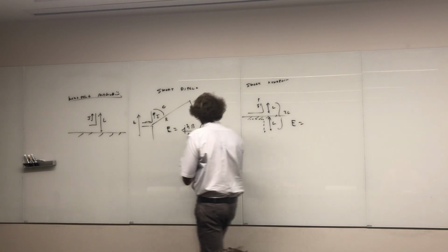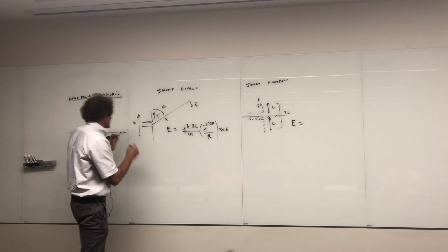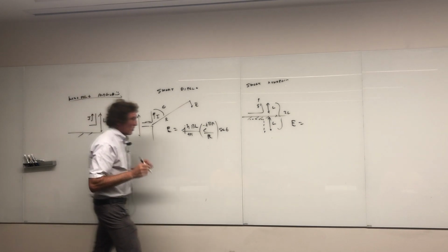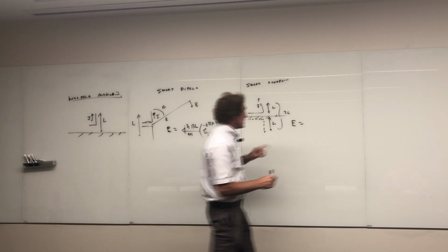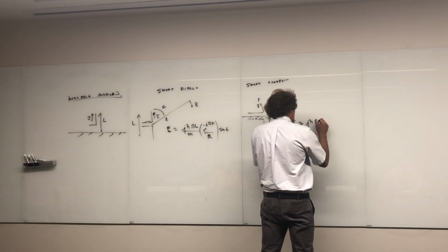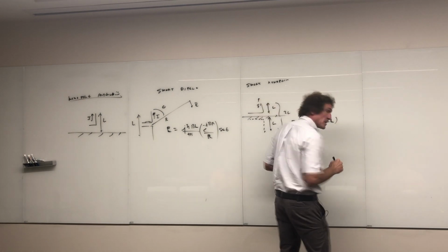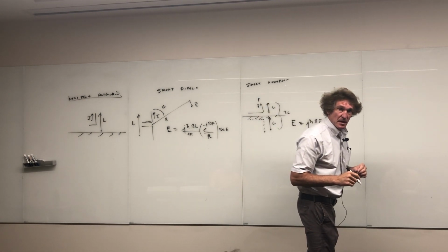This has a length L for the antenna. Over here, the effective length is 2L. So that's the difference for the E field. It's j eta beta I, but then it's 2L, where L is the length of the monopole. Follow me on this, class? Yes, sir.